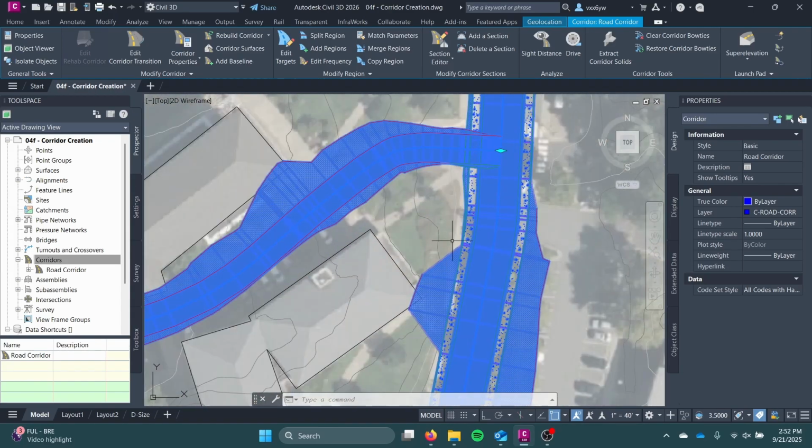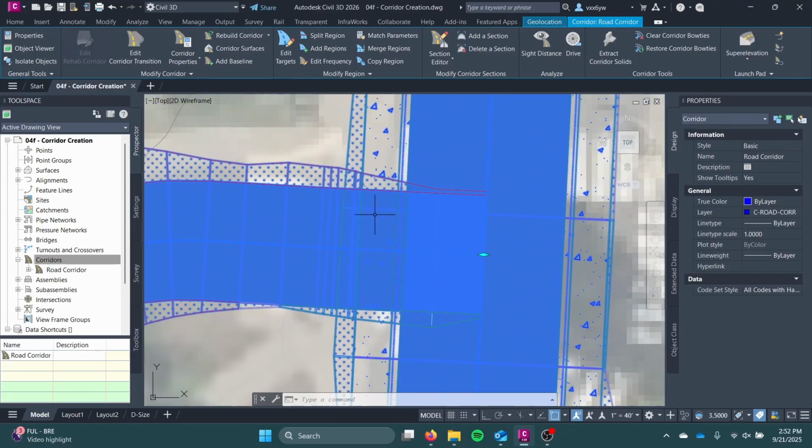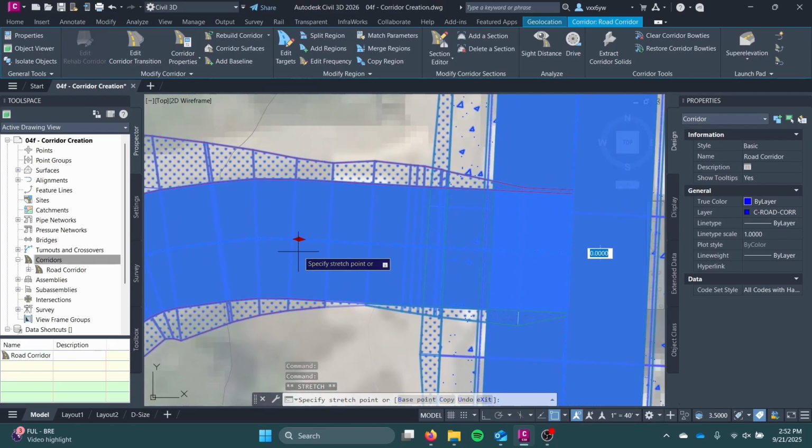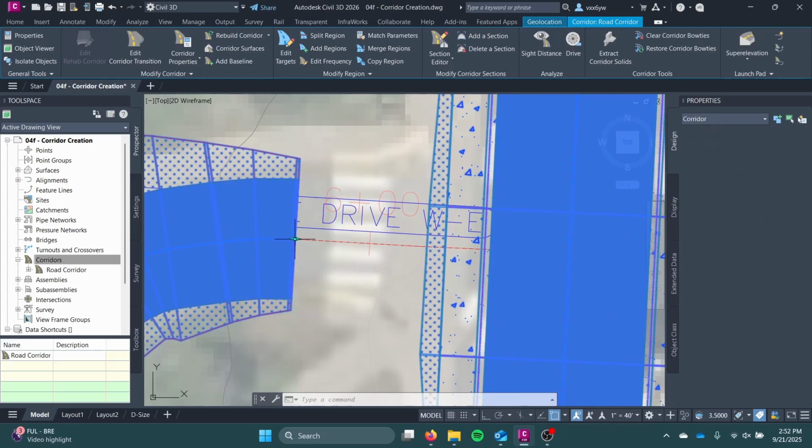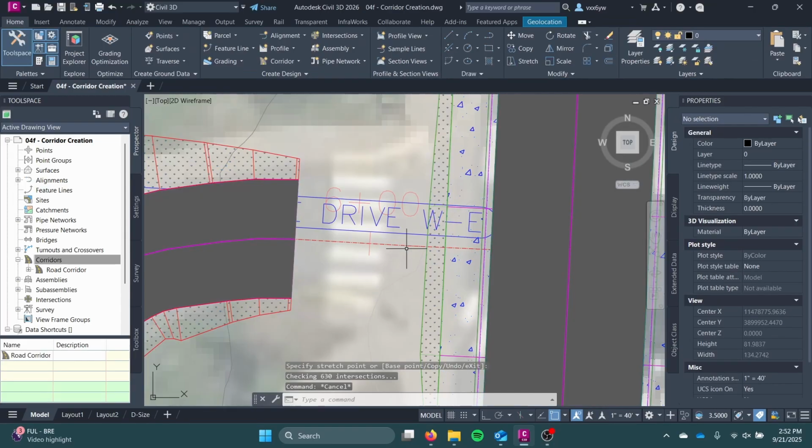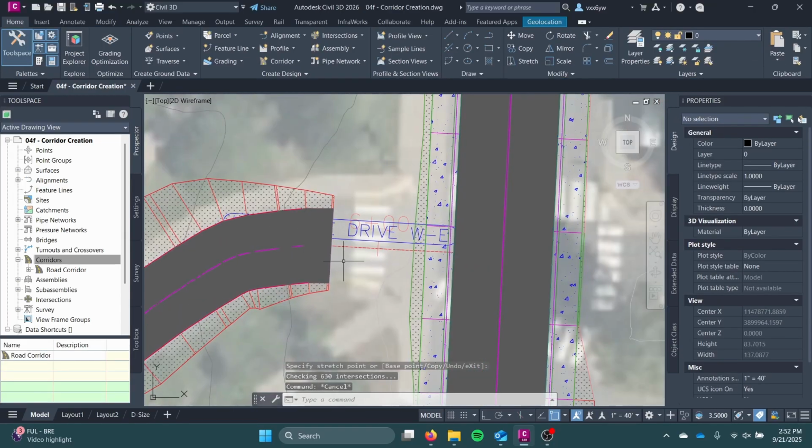And here I'm going to pull back Treehouse Drive because I don't want the Treehouse Drive corridor to render on top of Alderman Road. So I'm going to pull this back a little bit. And I'm going to pull it back a little bit farther than just the edge because we're going to create an intersection here, which will be different. So I'm just going to put this here. And you can see now that the corridor doesn't extend past where we moved that diamond to.